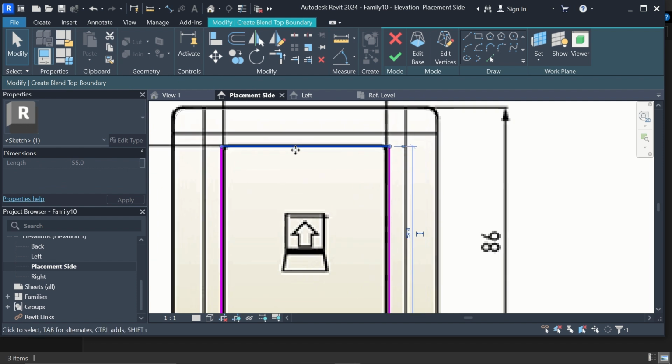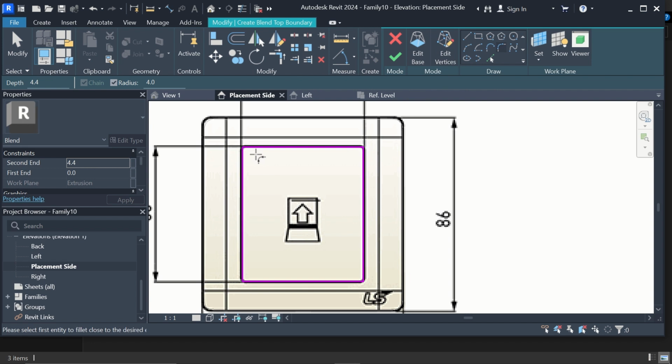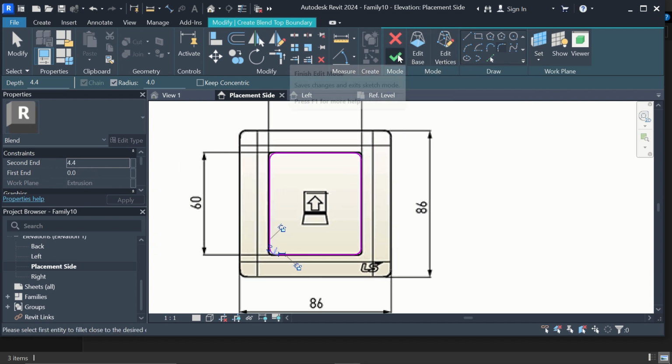So I'm going to move this down a bit so it covers the black lines. And then same for this area here. Same for here. So I'll go back here with my fillet set to 4 mm and apply the fillet arc command. Okay. So I'm going to change the thickness to 4, I'll leave it at 4.4. All right. And I would hit OK.